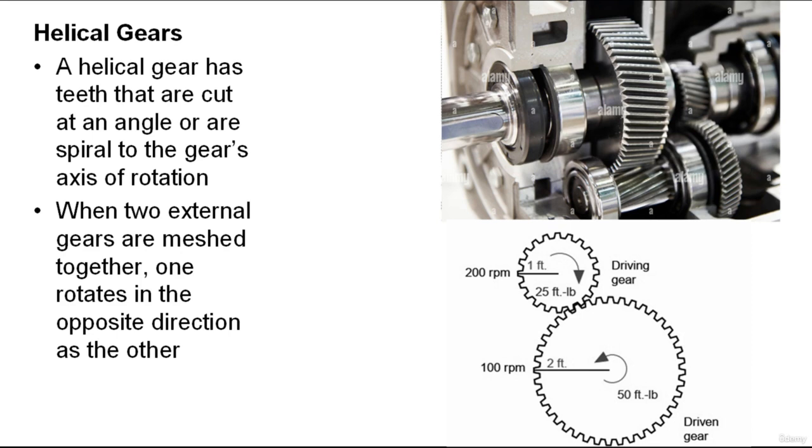One characteristic is that helical teeth on a gear cause the gear to move forward or aft on a shaft. Depending on the direction of the angle of the gear teeth, the axial thrust must be absorbed by thrust washers and other transmission gears, shafts, or the transmission case.